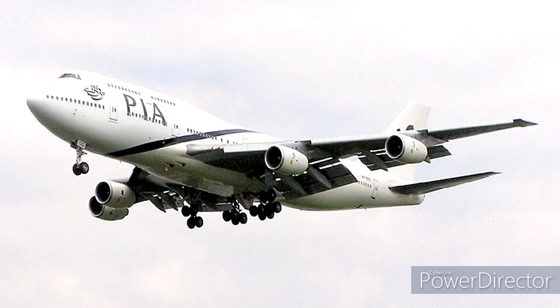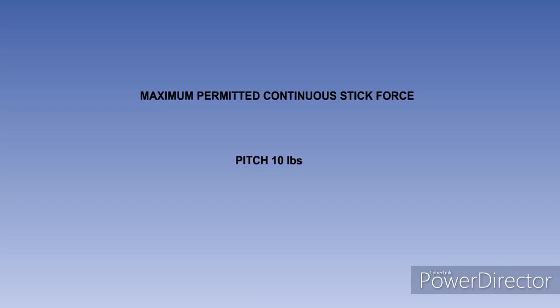As aircraft have become larger and faster, the increasing air loads have made it impossible for the pilot alone to have sufficient strength to comfortably control the aircraft. The maximum permissible loads that the pilot needs to overcome to operate the controls are specified in EASA regulations. They are, of course, subject to amendment, but just to give you an idea, at the time of writing, the maximum continuous stick forces allowed were 10 pounds in pitch, 5 pounds in roll, and 20 pounds in yaw.